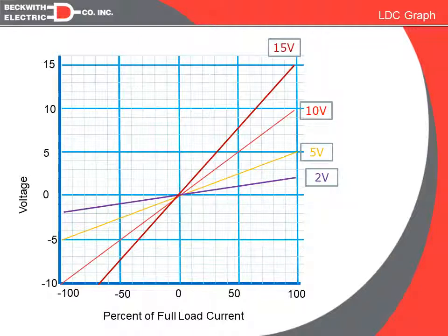The current really is still in the forward direction, just from a different source. We would consider that a reverse power, reversed from its normal source, but the current flow direction we would still consider forward, because it is going from its new source towards the load and not from the load towards its new source.